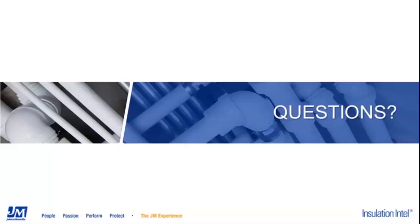Meredith, John, do you have any thoughts on this? Yeah, I think it's going to depend on what other aspects you're looking for. Do you need compressive strength? Is that something that would be important for the application? In which case, the Polyiso would be a good option.